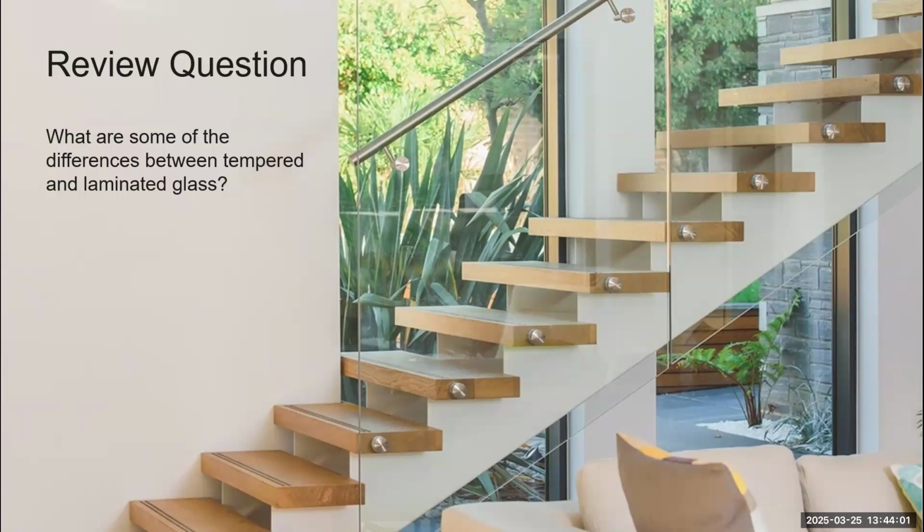How is the strength of the glass according to the region? High humidity and hurricane zones, for example. The strength of the glass that we will typically see in a hurricane region, we will start with 1-inch glass and move up to 1 1/4. You will have a base shoe that has some type of girth, sitting around 3 3/4 inch wide by about 5 1/2 inches tall, and it's a pretty substantial looking base shoe. But in reality, it's pretty transparent compared to the alternative of trying to solve that with an overall post and rail type of application.